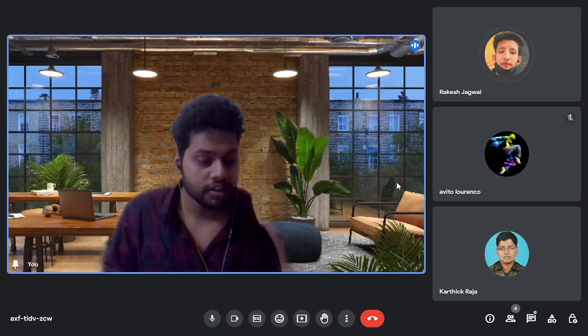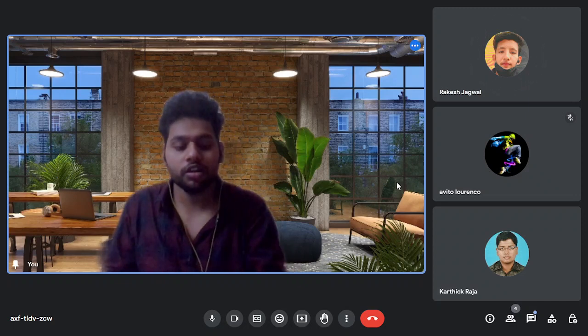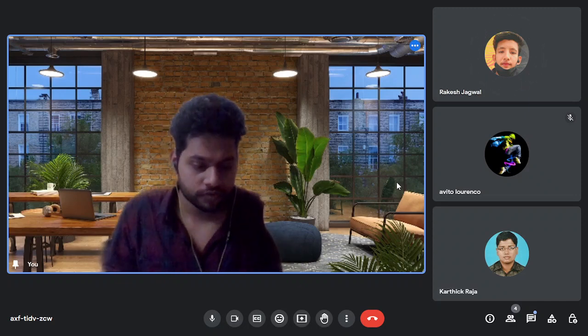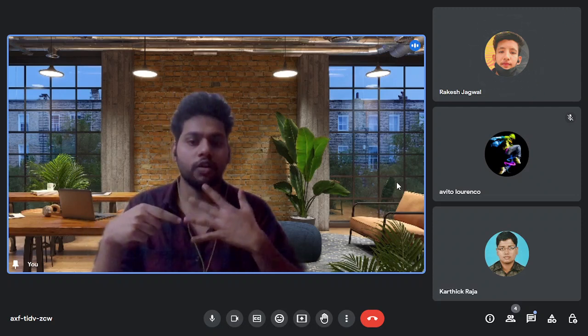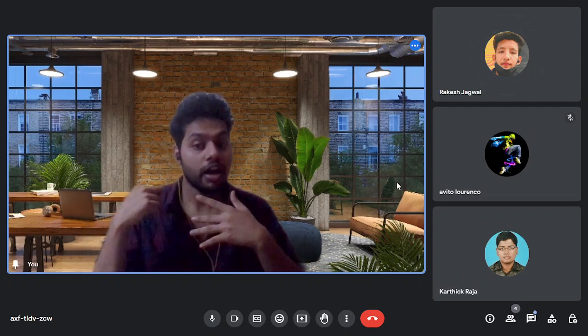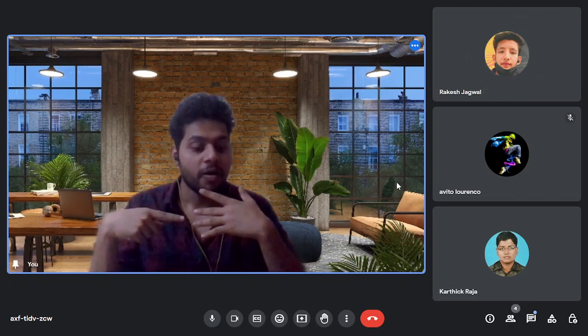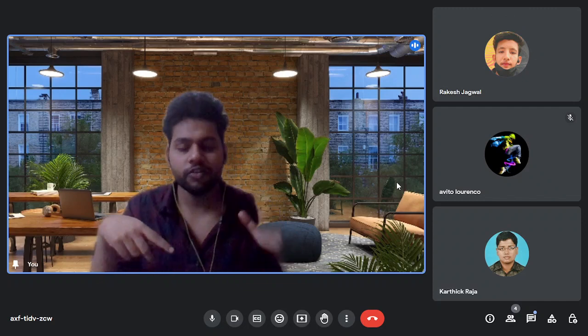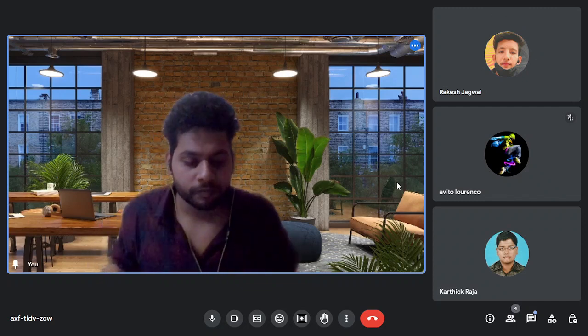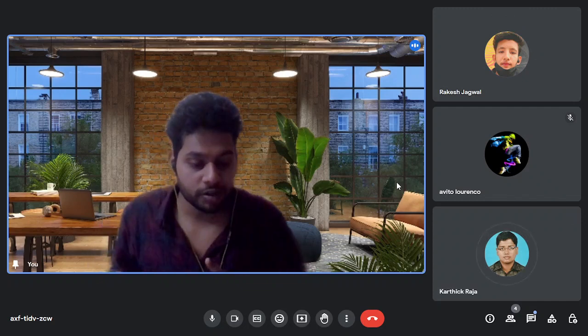A star connection has four components, that is the neutral and the three phases. Three phases means three hot wires for those three phases, along with the neutral in a star connection. While in a delta connection, only three phases. There will be no neutral.